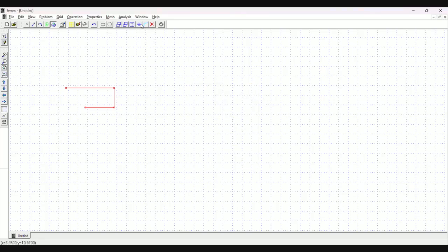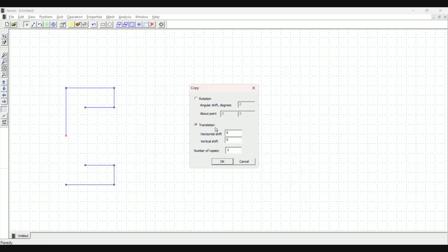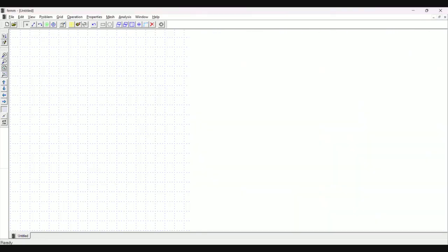Not a copy, we need a mirror image. So mirror image, and we have to define the point of symmetry. So mine is x-axis, so done. And also I need an air gap here, which is -5 and 0.1 mm in height, which means 0.1 by 2, half on both the sides, above and below. I would have done this before, I just forgot. It's not like we have to do it this way. Horizontal shift is 2.